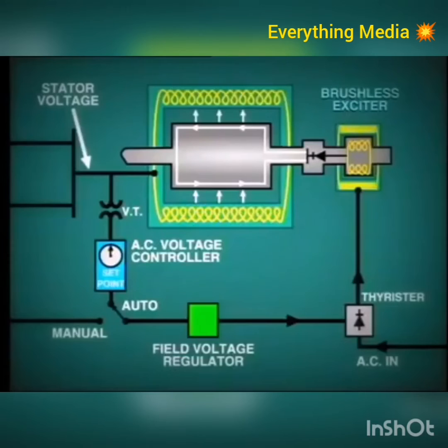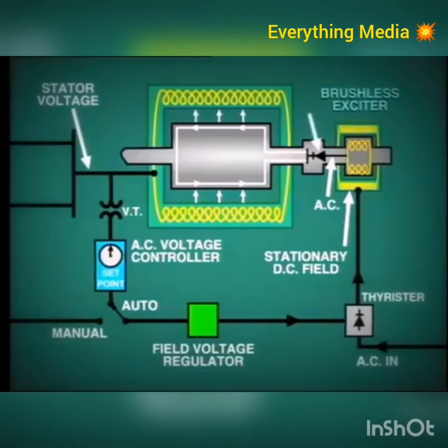In this exciter, a stationary magnetic field is provided from the DC winding, which is wound on the stator. The rotor winding produces AC voltage, and this is fed directly into diode-type rectifiers, which are built into the shaft. So we have, in effect, a rotating rectifier. The DC output from the rectifier is connected directly to the main rotor winding through leads which pass inside the shaft. There is no need for collector rings or brushes.